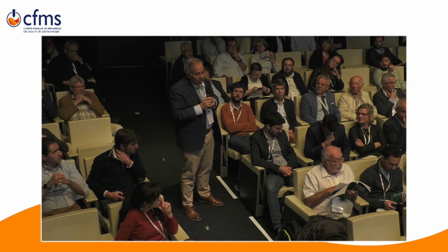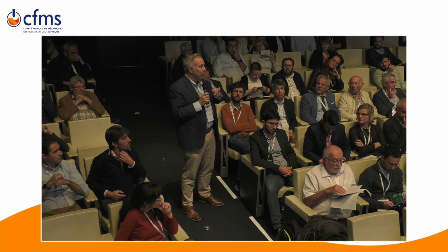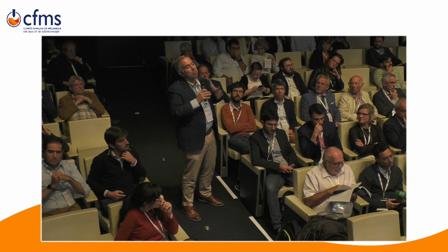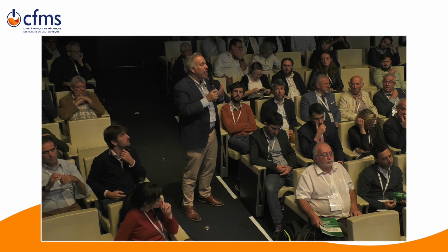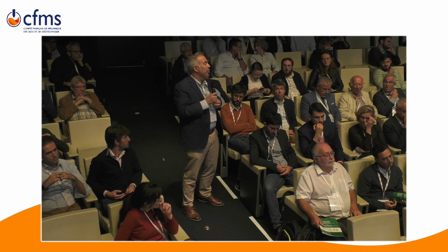Another difference we saw in the piles, perhaps also applicable here, is that the dilation that takes place in the shear band is much larger in the small model, because the shear band is comparable to your structural element, while in reality your structural element is much bigger compared to the shear band. So the trick we applied was to model the centrifuge test with an interface that captures what's happening there, validate the model, and then go back to reality, changing the interface properties. I was wondering whether you think it's an analogous problem, and if such a methodology could be of interest.